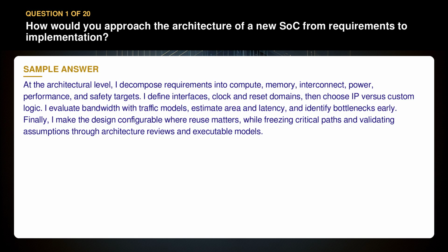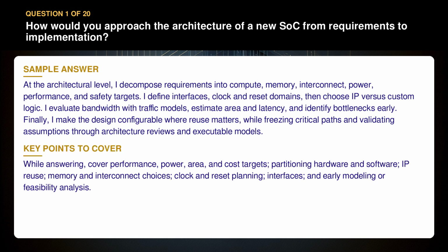Finally, I make the design configurable where reuse matters, while freezing critical paths and validating assumptions through architecture reviews and executable models. While answering, cover performance, power, area, and cost targets, partitioning hardware and software, IP reuse, memory and interconnect choices, clock and reset planning, interfaces, and early modeling or feasibility analysis.